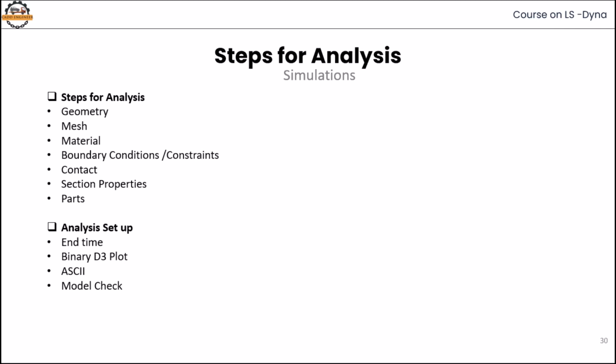After doing all this, you have to attach everything into parts, like section ID and material ID. If you're doing blast and other kinds of problems, we also have to define the EOS, equation of state, and Hourglass equations. Those kinds of things have to be defined in parts.